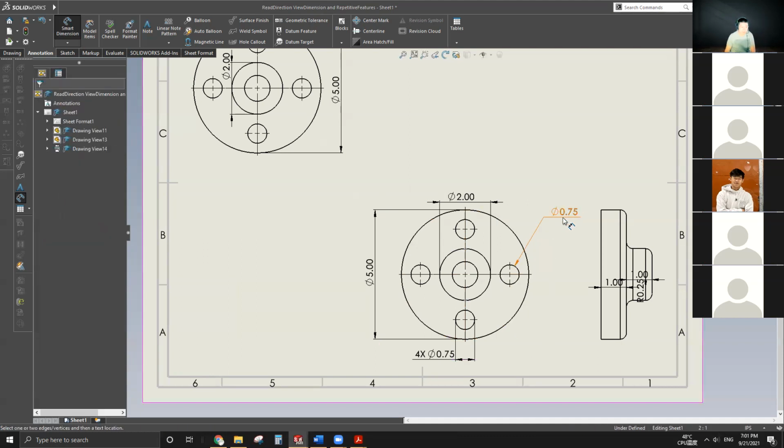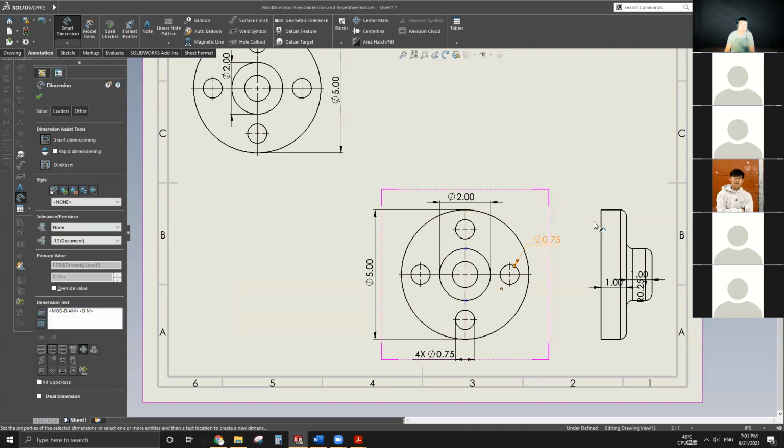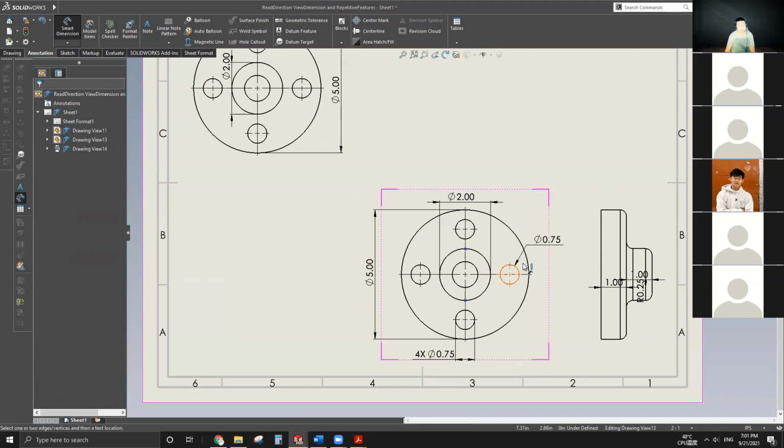Yeah, most likely it's going to be presented like this, with the horizontal text and just an arrow pointing to the hole. For circular subjects, normally just ODs, use the two extension lines with the number in between. So this 2 inches in diameter is okay. It's good. This 5 is not good, because we're supposed to keep all the numbers at a horizontal level, not vertically.